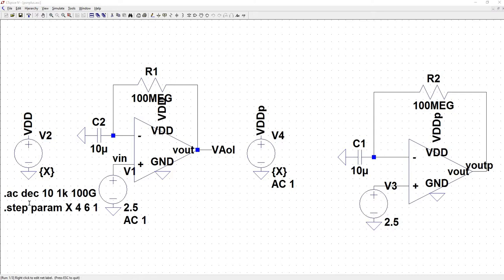So this one's taking a little bit longer. Alright, so this is taking kind of an absurd amount of time. We'll see once it gets to when it's stepping the source to 100%. We'll see what happens. Okay, so now it's doing this crazy fill-in thing, so I'm going to go ahead and halt the simulation. Failed to find DC operating point for AC analysis.